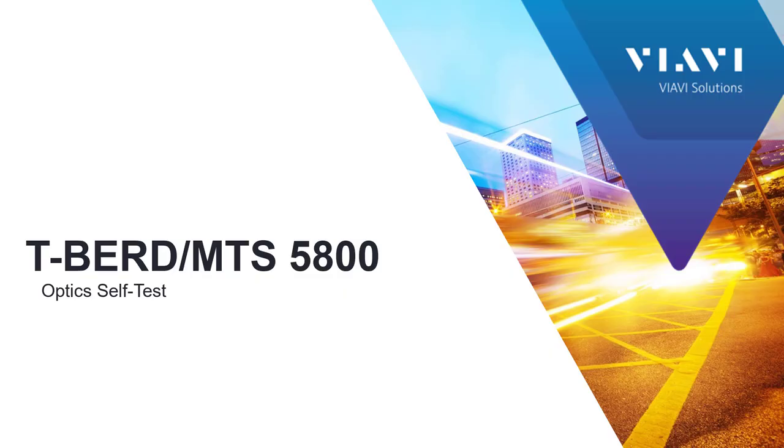So what you would need is, of course, a T-BERD 5800 unit and the test option for the optic interface that you want to test. So maybe a 10 gig Ethernet test, or 25 gigabit Ethernet, 40 gigabit Ethernet, or 100 gigabit Ethernet. You'll also need a patch cord that you will be able to connect from the transmit to the receive of your optics, so that we can run the test through the optic self-test.